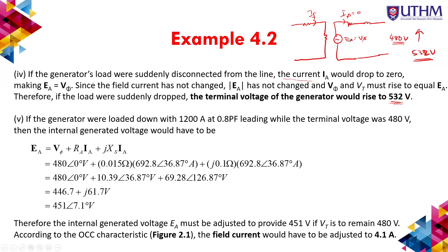You can see here that EA is much bigger than V phase. This is due to the lagging load.